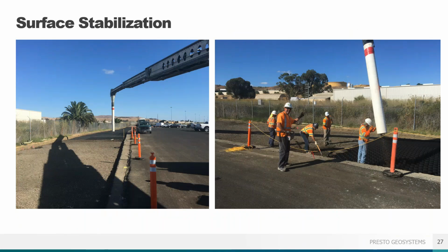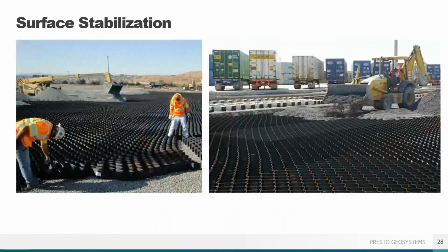There are many ways to place the infill. A rock slinger is one of them. This allows precise placement for fast, even filling while controlling the height from which the aggregate falls. Buckets with extendable booms can also be helpful, though a push with a dozer or backhoe will work just fine.